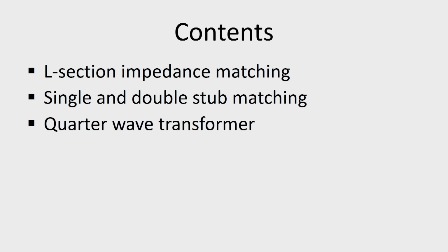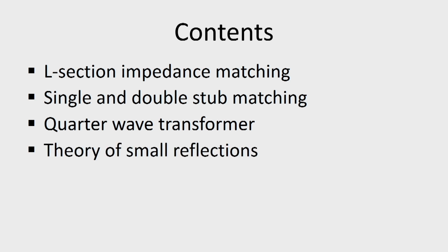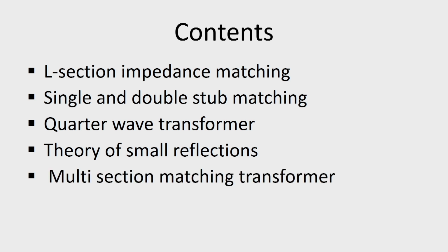Then we will see a very interesting matching circuit which is called a quarter wave transformer. We will discuss the theory of small reflections, and then utilizing the theory of small reflections we will discuss how multi-section matching transformers can be designed. Then we will consider another form of matching network which is a tapered line. This type of tapered line can be easily designed using planar transmission lines.